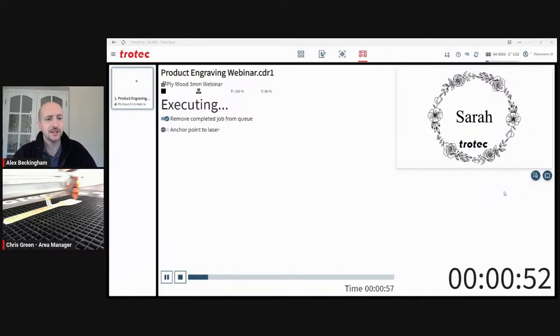It doesn't allow you to do the kind of overview within the Ruby software positioning, but it does mean if you work with any printers, typically it tends to be a lot of UV printers for the laser processor, so that you can print directly to substrates such as acrylics and woods. With that system, the camera on the head picks up the pre-printed registration marks, and then can scale all of the artwork and the positioning to make sure you've got a good cut position to the print. Yes, but we've had that for a long time now. It's a very, very useful part of the machines, and it's quite necessary in some print and cut applications.